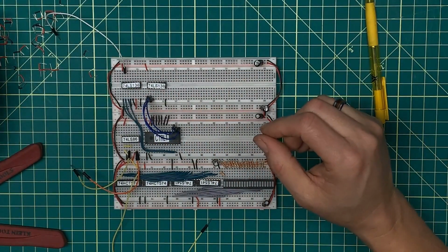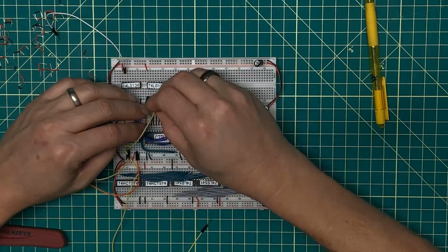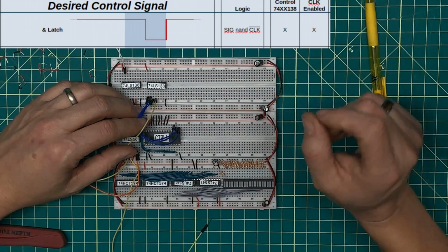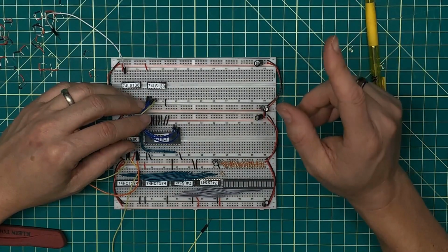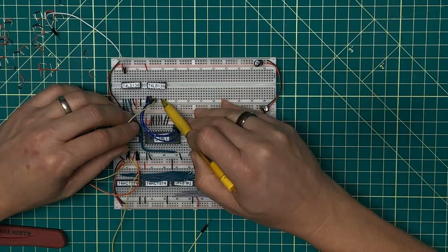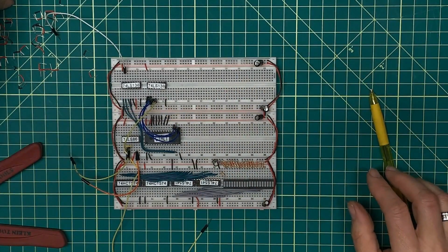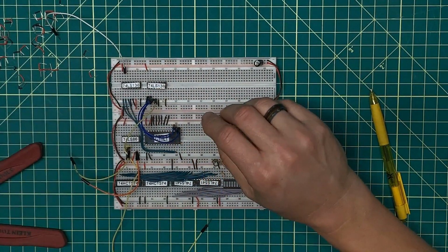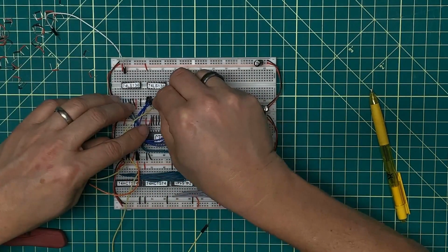And then I can take this clock over here to one of the active low enables. Now, in my drawing, I have an inverted clock, which would be high at the period of time that I want this to be asserted. I could use the inverted clock and put that into the active high signal, or I could use the uninverted clock and put it into one of the active low signals. I chose the active low signal for no other reason than I've got two active lows and I may need to hang on to that active high for something else. I'm not quite certain yet.